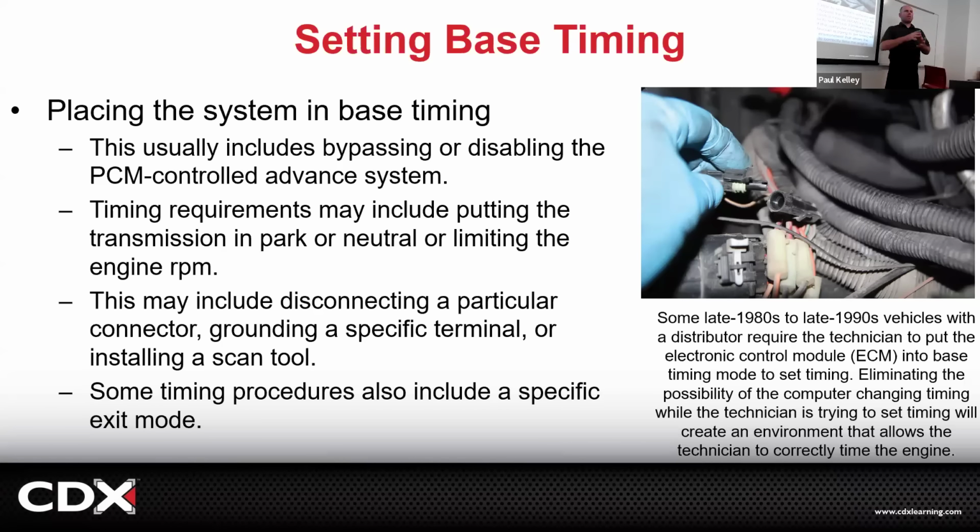If there's something wrong with the timing, the onboard diagnostic system is going to set a crankshaft, camshaft correlation, or get a set of codes. But on a distributor, the timing was controlled literally by where the technician sets it. So if it's a car that has an adjustable distributor, that's one of the checks for smog. They're supposed to connect their timing light.